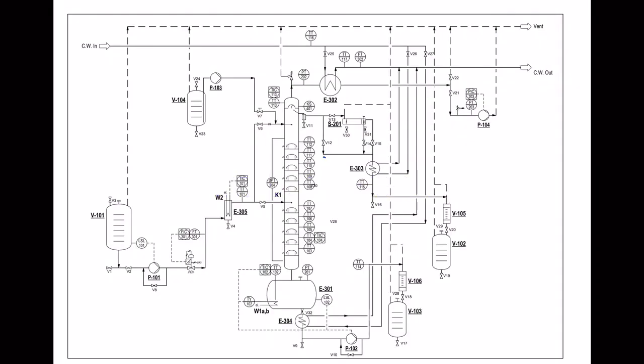Okay, now we proceed with the experiment procedure, which relates to the batch distillation at total reflux. In this experiment, there are two objectives to be achieved. Number one is to determine the number of theoretical plates or stages at the total reflux for different liquid and vapor loading, with heater power of 50% and 75%. Second objective is to determine the effect of the liquid and vapor loading on the theoretical number of stages at the total reflux. This experiment can only start after you perform the general startup procedure.